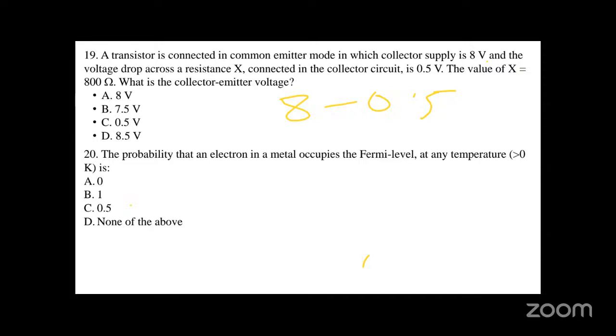One of the questions asked has to do with the threshold voltage, or the barrier potential, which for silicon is 0.7 and for germanium is 0.3. This is a similar equation. If the barrier potential is 0.7, you will need a voltage greater than 0.7 for current to begin to flow across that junction.